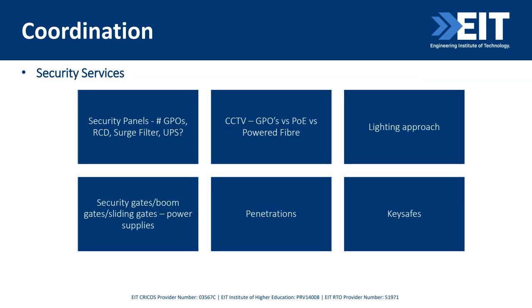Security, very similar. Where are their security panels? What do they need? Do they need general power? Do they have CCTV? Does our lighting need to be of a specific level for their CCTV to operate? Where are their security boom gates or sliding doors? Key safes, any particular equipment they have.